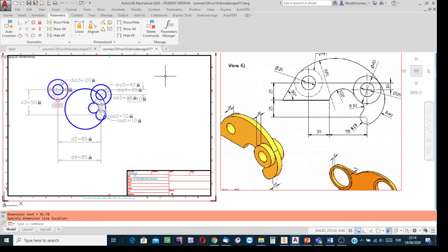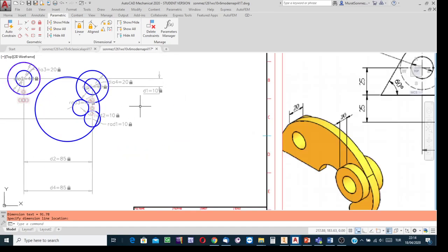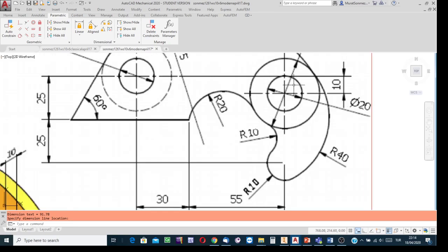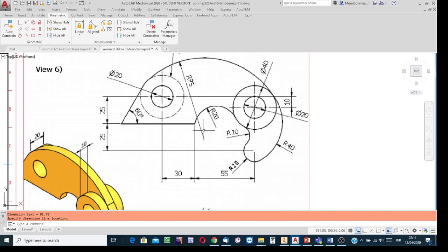And then check after sizing it whether it is still at the correct side. I see from this projection that the center of the available circle, this is the available circle, to which this arc must be tangent, is at the inside. Saying inside, I mean see the region bounded by this circle arc, and this region is bounded by this, so it is inside. Okay, the other side is the outside. Well, the center of this is at the inside, the center of the other circle is at the inside.